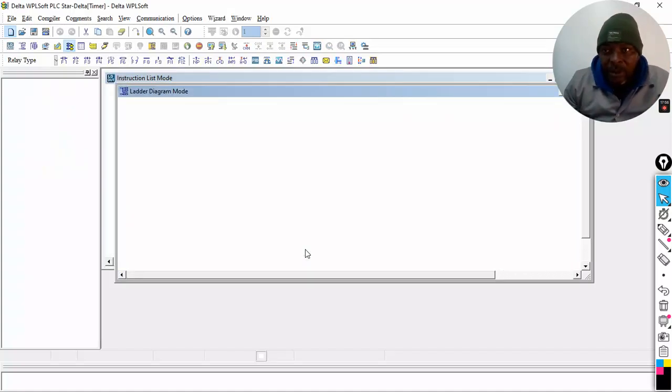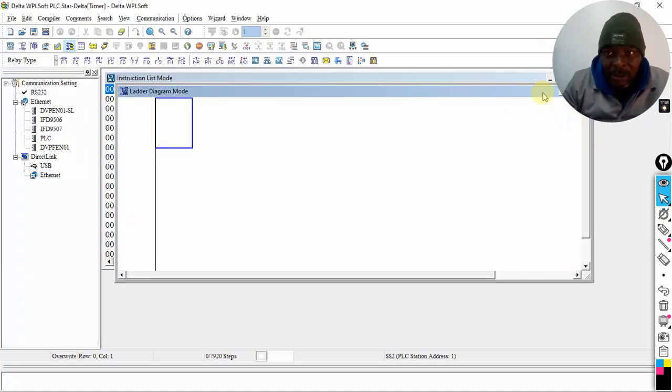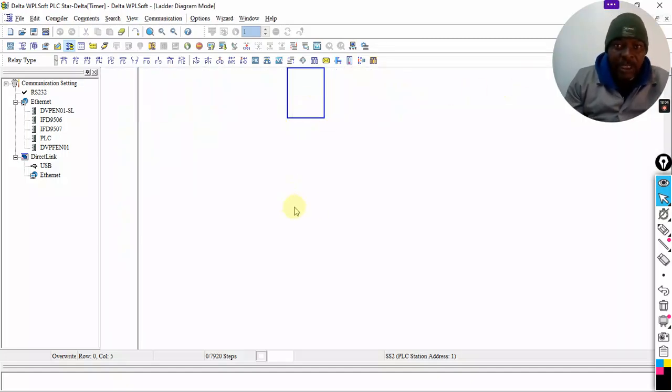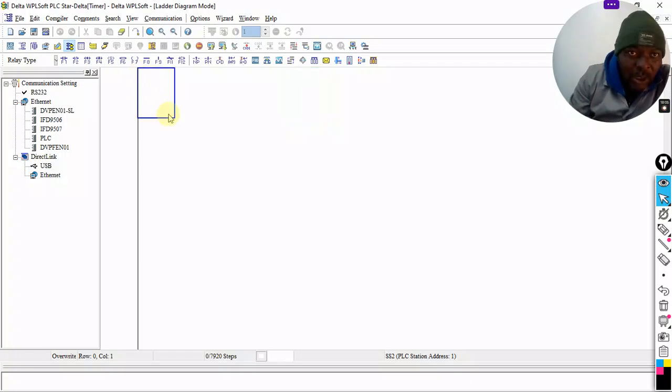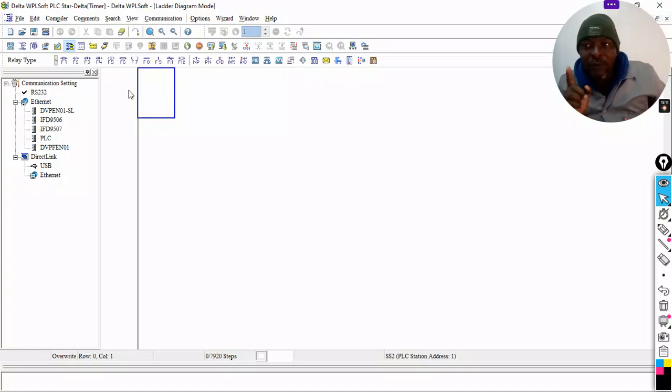So there we go. All I need to do now is double click and hope it works, because now my picture is out of the way. We'll remember that we need an overload. So do we wire the overload to the PLC? We can if we want to, but the overloads can be wired separately. I might not include that part. It depends. When it comes to a test situation or a working environment, it will depend on what the preference is, what the workshop manager decides they want. What do the engineers decide is the best operation?